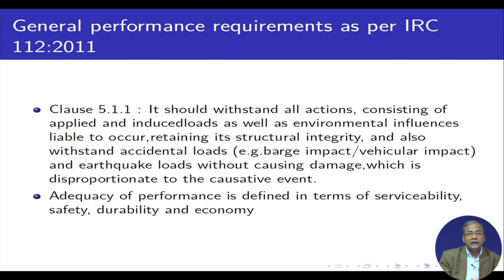It should withstand all actions consisting of applied and induced loads as well as environmental influences liable to occur, retaining its structural integrity, and also withstand accidental loads, as for example barge impact, vehicular impact, and earthquake loads, without causing damage which is disproportionate to the causative event.